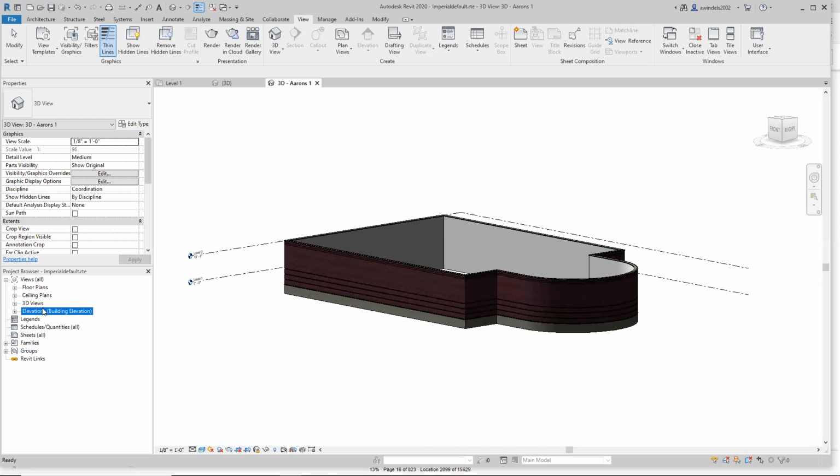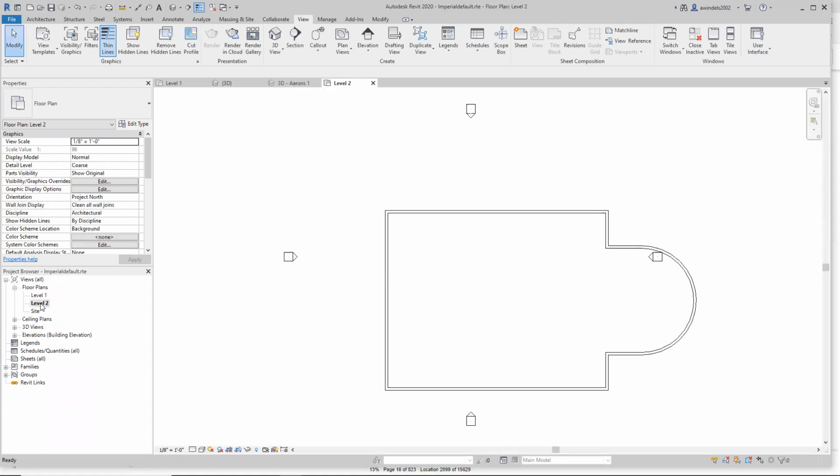We're going to go into level 2 of the floor plan, okay? Double clicking it, left click, takes us to it. That's step 3 on page 32. The wall looks a little different than level 1, right? It's because your display is set to coarse. That's part of it. They want you to make some changes, possibly, but you could change it to what you need, depending how you want to see it.